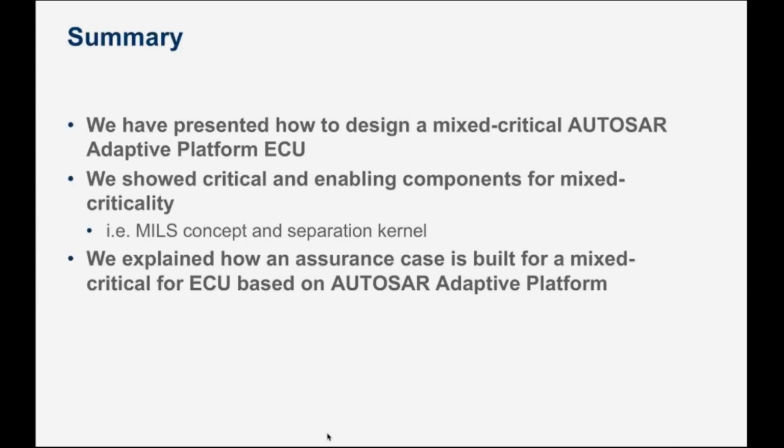So in summary, we presented how to design a mixed-critical AUTOSAR Adaptive ECU by using a separation kernel. We showed critical and enabling components for mixed criticality. This is the MILS concept and the separation kernel. And we also explained how an assurance case is built for a mixed critical ECU and how this is applied in this area.